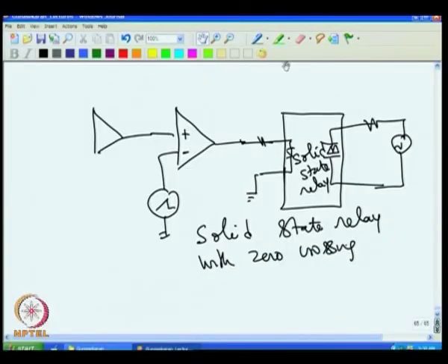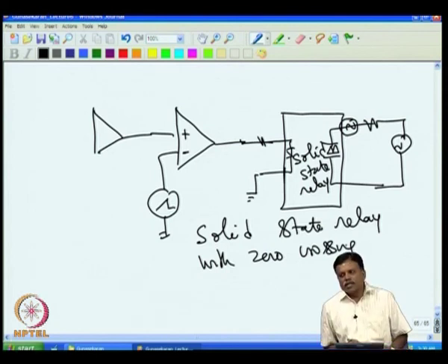The thyristor, one good thing is the thyristor can be protected using a fuse. In fact, this is the only device in electronics that can be protected using a fuse. No other device can be protected using a fuse. So in case of a thyristor or triac, one can give a protection with a simple fuse added, and when a short occurs only the fuse blows, not the thyristor, if the proper fuse is put. But using a fuse you cannot protect a MOSFET or IGBT or transistor. Always the fuse is protected by these devices, not the other way around.